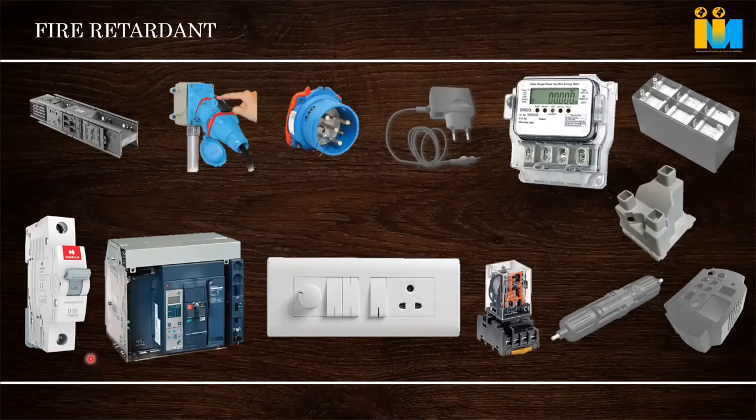So we can see, like busway, a lot of electric busway is there. This is a connector in PBT. Normally for higher electrical applications, thermoplastics like PBTs are used, or thermoset also. Thermoset is extremely good for electrical application. All the good electrical properties, thermal properties, dimensional stability are there. Then PBT, nylons are very good. PBT glass filled. Sometimes PC-PBT is also used when we want higher dimensional stability.